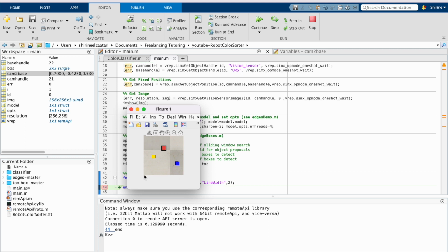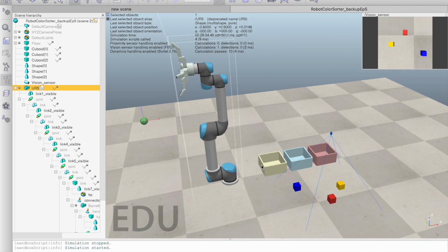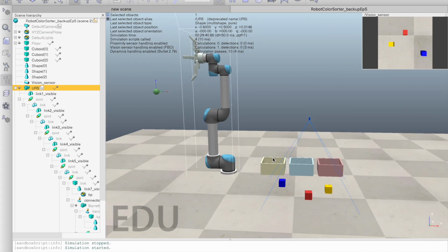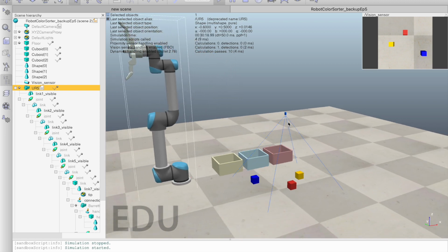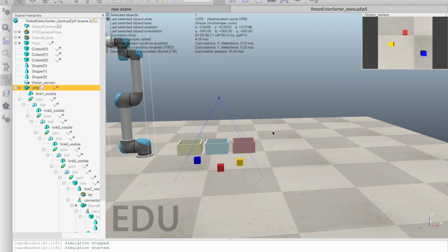But what is this distance equal to in real life? So if you go here, we need to find the measurement of this distance on the floor, from this side to this side. And that can be calculated because we know the height of the camera off the ground, so that's fixed, and we know the perspective angle.